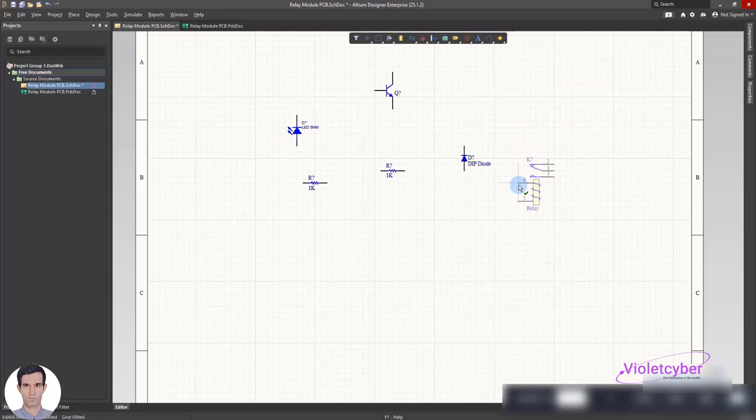First, I'll place the relay like this. And as you can see here, this output section is the relay terminals. In fact, this is the part that connects to the terminals. And in this part, these two pins that you see are the coil pins, or the power pins, of our relay. Well, if I want to consider this side as positive, that is, this side of the pin, I will place the diode like this here.